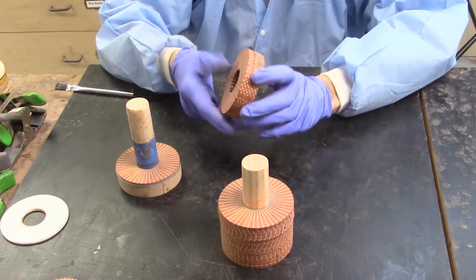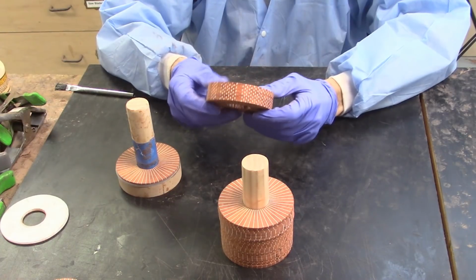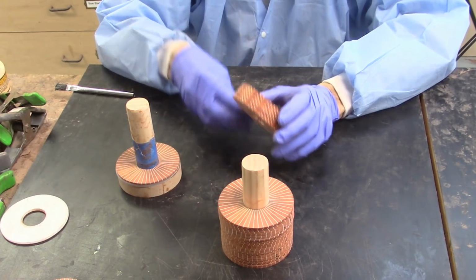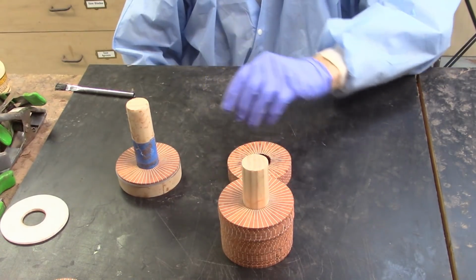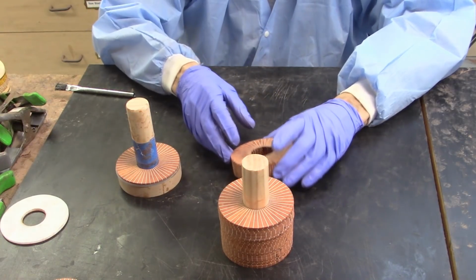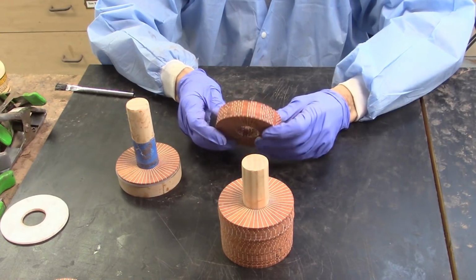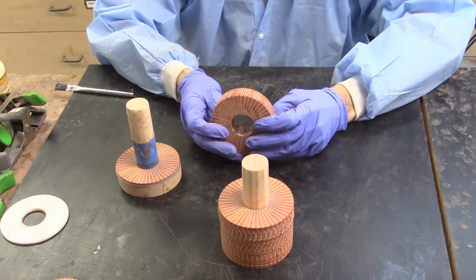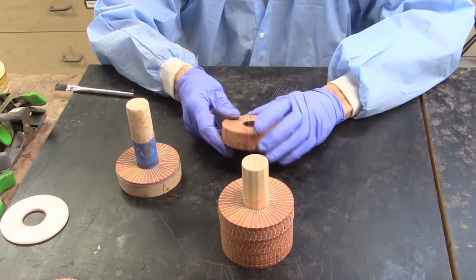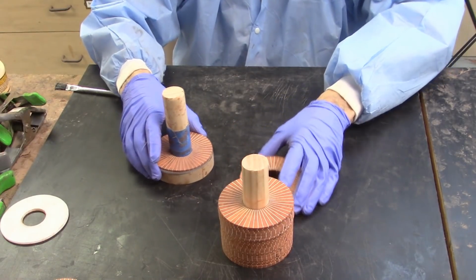This is a set of 10 I completed already. And I'm not using epoxy for these layers. I'm using Titebond 2 glue. And the reason for that is the epoxy just slips and slides too much. The Titebond 2 will set up a little bit quicker. It's just much easier to set them and get them so they don't move and go a lot quicker.